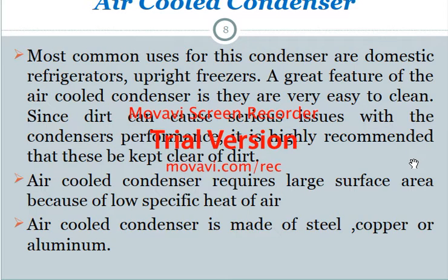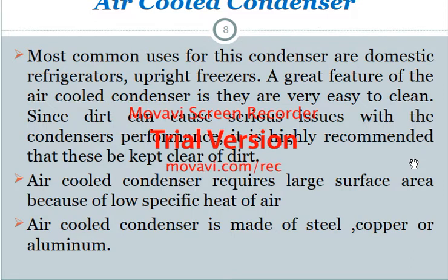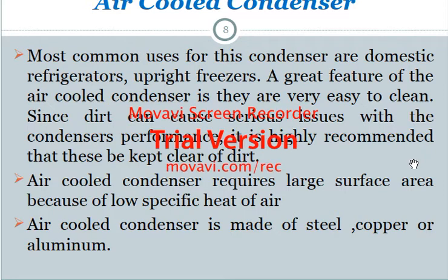As we know, the fin itself has small spaces within it, and dirt from the air will attach to the fin, so we will keep it clean, because it will affect the process of heat transfer.